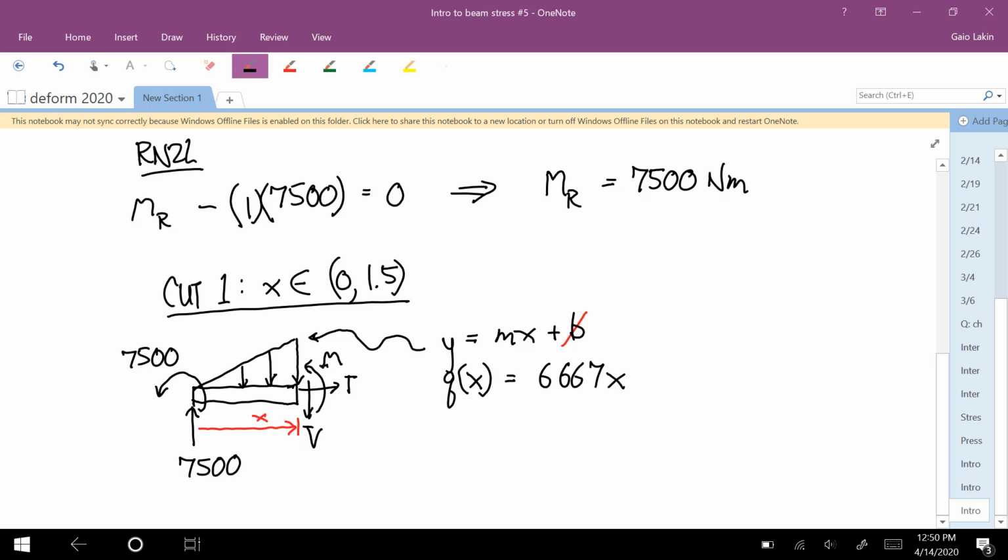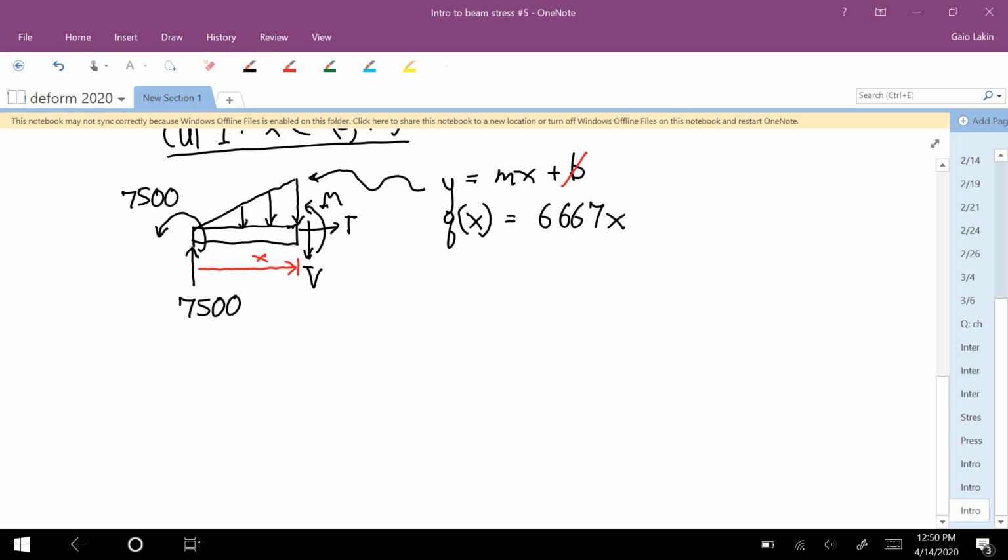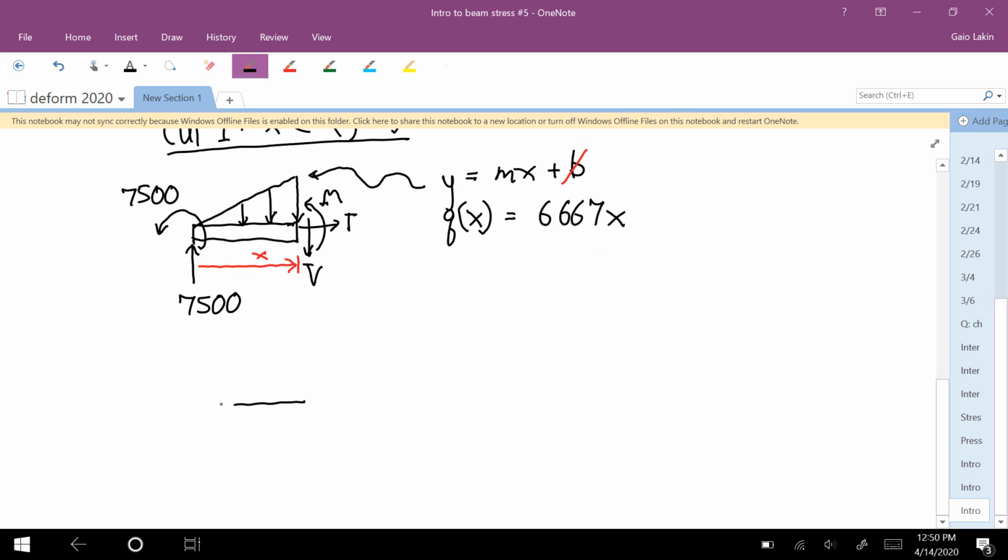There's no torques in this problem. And now I can redraw this free body diagram. We've chosen the piece that we're isolating. So we still have these point loads at the left. And the distributed load acts 2/3 of the way from the left to the right. The magnitude of that force is the base times height over 2.